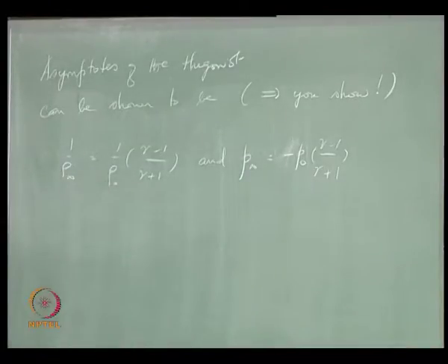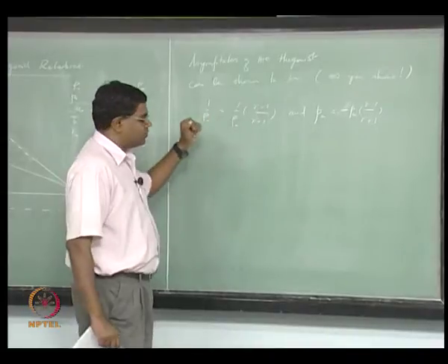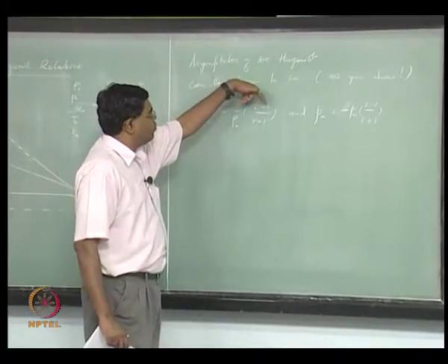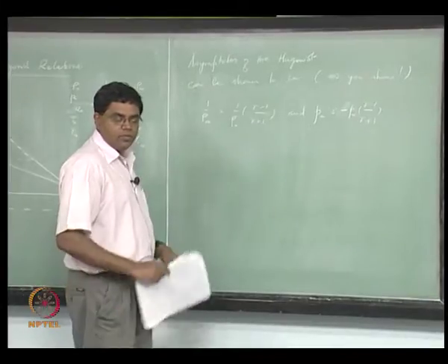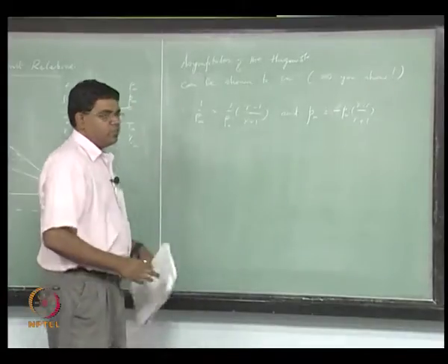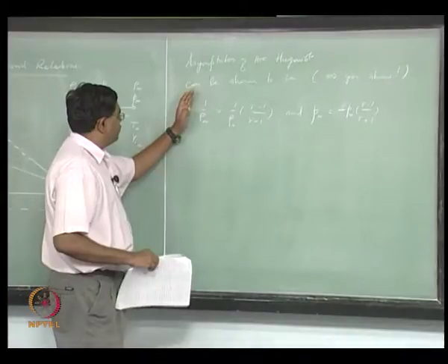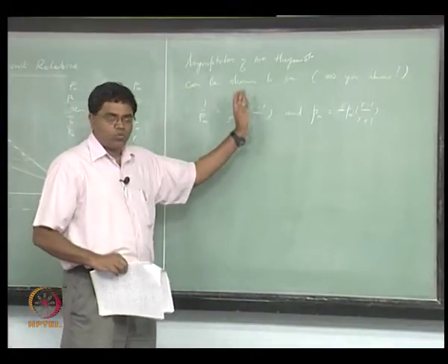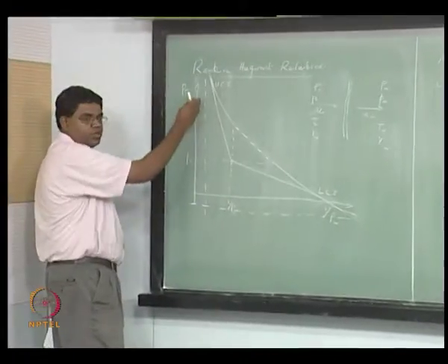Now notice that gamma is the ratio of specific heats, which is greater than 1, so let's suppose it's about 1.25 or something like that. So this is going to be like point something divided by 2 point something. So gamma minus 1 divided by gamma plus 1 is always less than 1, and so 1 over rho infinity is always less than 1 over rho naught, and therefore your asymptote is going to be to the left of the origin.